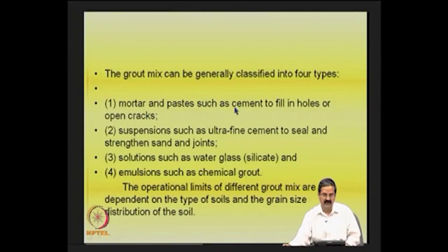To understand further on this, we can classify the grout mixes into some 4 classification groups: mortar and paste such as cement to fill the holes or the open cracks, then suspensions such as ultrafine cement to seal and strengthen sand and joints, solutions such as water glass, and emulsions such as chemical grout.